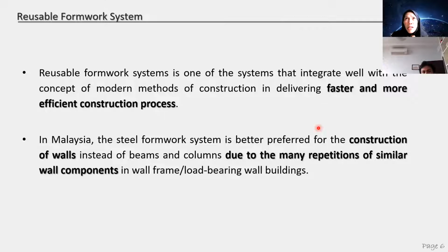You use it about 2 to 3 or 4 times, and the soffit or the plywood of that formwork might deteriorate and have defects, and it will cause construction defects to the component.